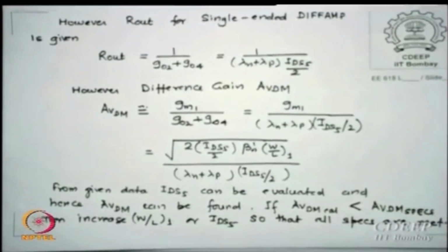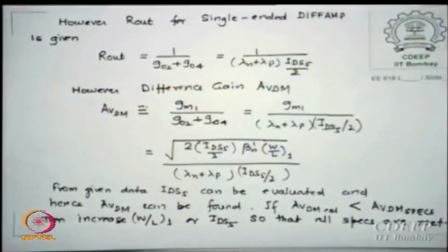So please verify which term, GM by IDS, I told you now. Please take it GM by IDS I am looking into, this will decide my GM part, IDS will be decided by the other three. So my design parameter therefore is GM by IDS, not GM, not IDS, though I can independently look for them, but the ratio should be used by me as my design specification. Is that clear to you?